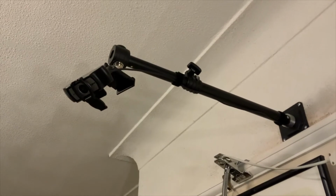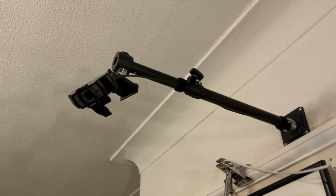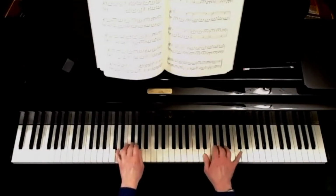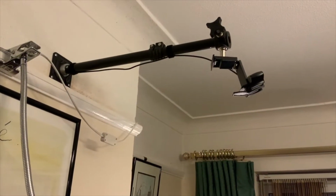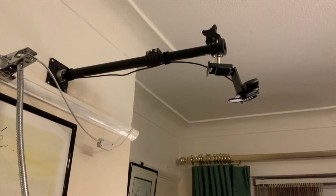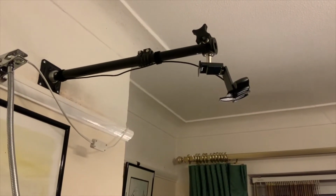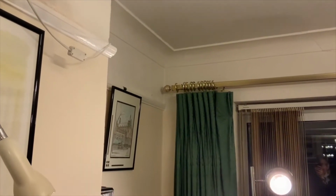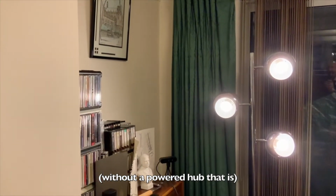These webcams give reasonable results, but not brilliant results on objects that are not human faces. Typically the contrast tends to be too great, I find. USB 2 cables can be extended to about 5 meters without any problems, but USB 3 are more problematic and probably only extendable to 3 meters.